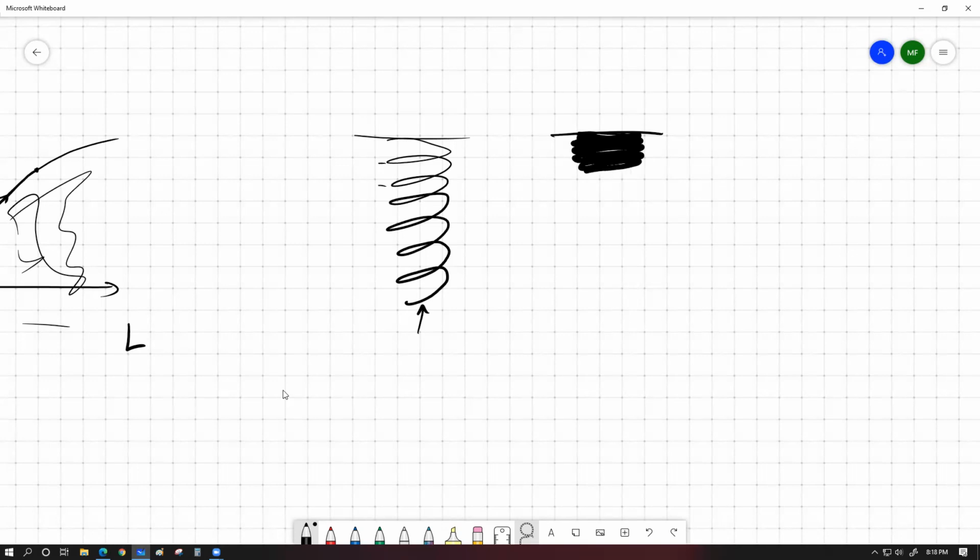If all of these gaps go away, what's going to happen? The coils are simply going to touch each other side by side, pretty much like the fingers when you are making a fist, other than the thumb. So they're going to pretty much touch each other side by side. So at this point, if we still try to apply force onto this object, this is not going to behave like a spring. Now it is pretty much like metals are stacked upon each other. So up till these gaps are available, it's going to behave like a spring. Whenever these gaps become zero, this is going to work like a solid hollow cylinder, because the metals are touching metal. So now it's not going to behave like a spring anymore. It's going to behave like a much stronger object.